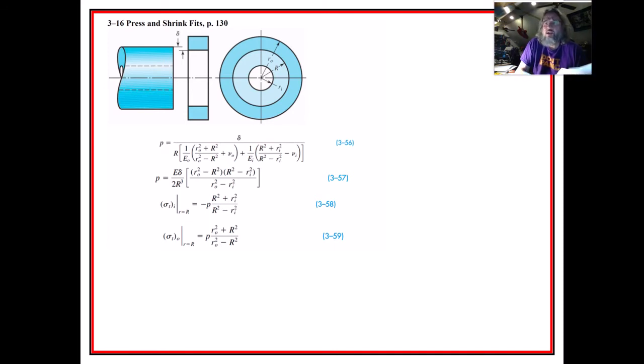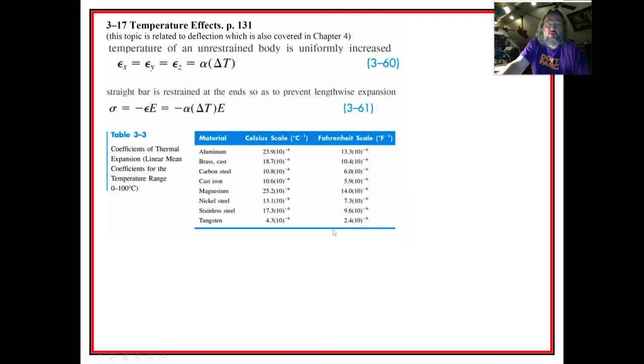So anyway, this would be an interesting thing to find out. One reason you might want to know this is because these parts might also be in operation. Heck, they could be spinning, because now some of the other stresses that they might experience might be because of rotation, right? You need to combine stresses, and you need to combine stresses intelligently in order to calculate what the actual operating stress is going to be, or to go backwards and design it so that it doesn't fail.